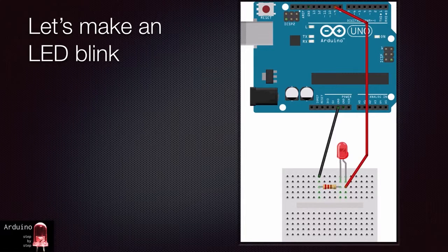With the background and theory behind us, let's implement our first Arduino circuit. The aim is to become familiar with plugging components into the breadboard, uploading, and running a sketch. In our first sketch, we will simply make an LED blink on and off. Here is a diagram of the circuit you need to build now.